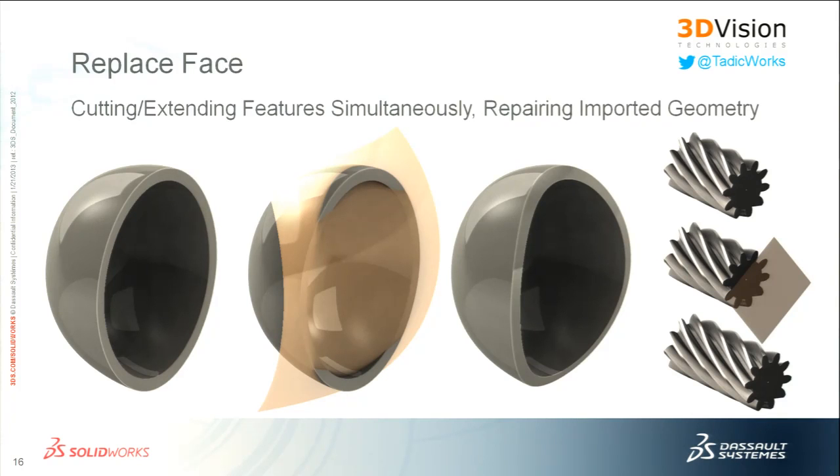So the question was, how would we dimension or constrain the size of the circle that was used for the replace face on the star cutout? The surface that I created was the extrude surface, which is a sketch-based feature just like the extrude feature is. So just going into that sketch and adding a dimension to that initial circle that I drew would constrain the size of it. And then I deleted it, yeah.